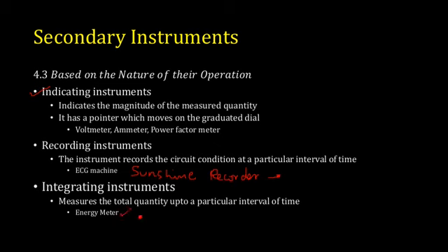Energy meters fall under this category. Once your energy meter or KSEB meter is installed at your premises, it starts reading, and every time it adds up to its previous reading, so your reading increases. It is basically integrating the value and adding it up, and you will be getting new values every time. Such type of instruments are known as integrating type instruments.